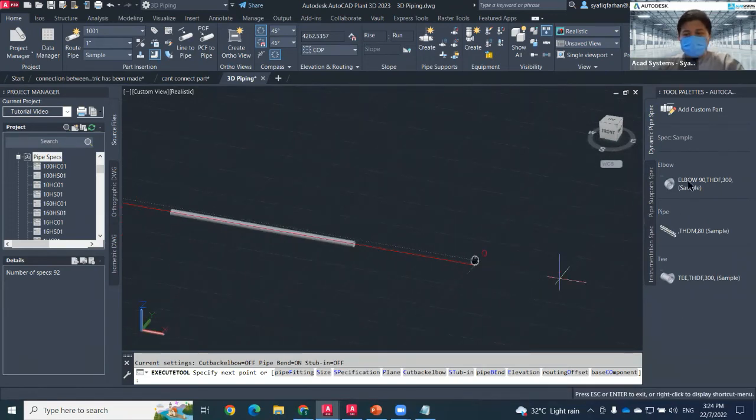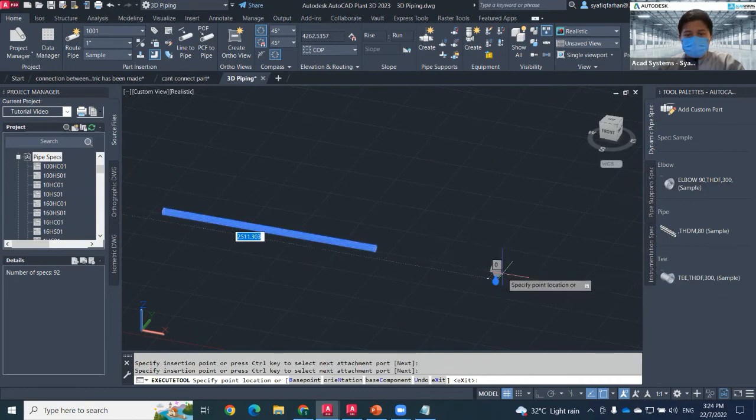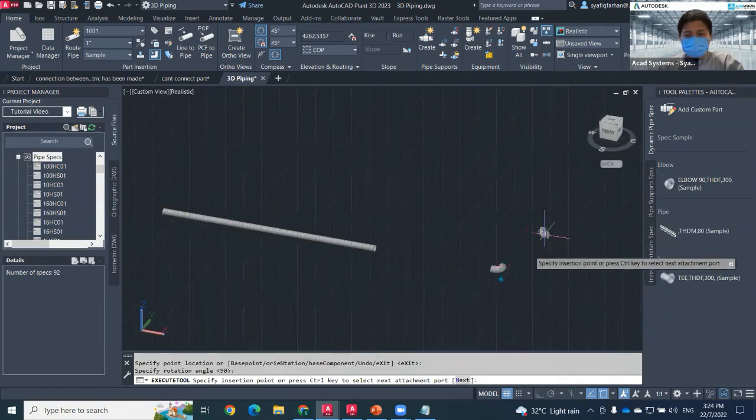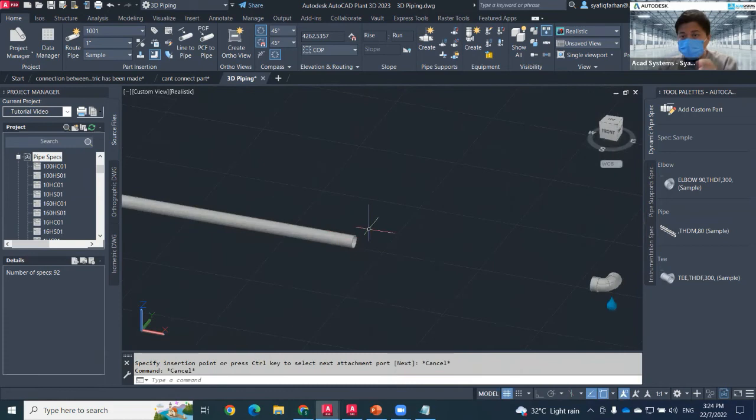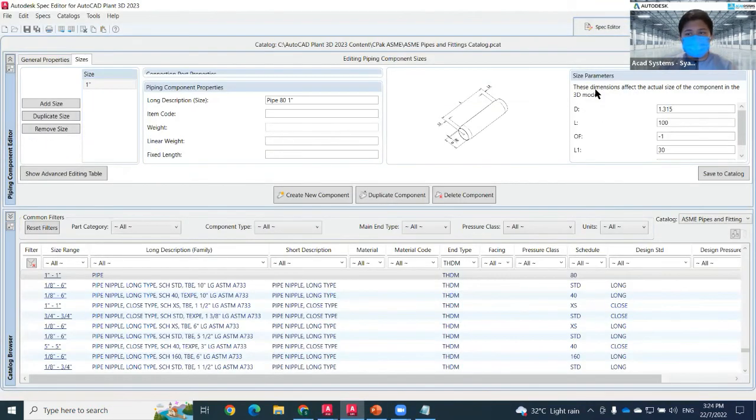So this one, my engagement length is wrong, so I need to repair it back. My elbow can be inserted here without any problem, but the problem right now is my engagement length. From my catalog, this object, the length here, this L1, I need to make it 1 only. L1 and L2, 1 only. That will be the problem for my drawing actually.